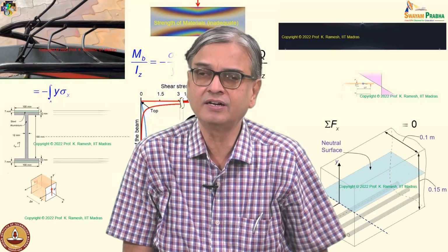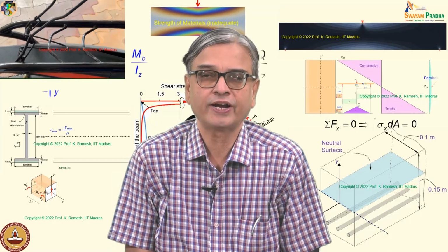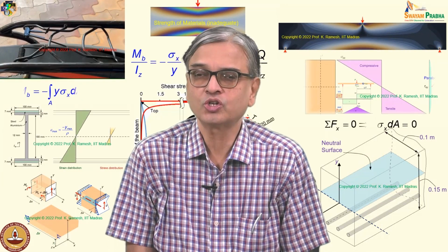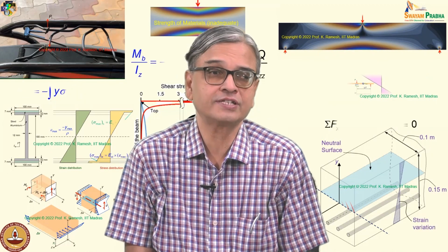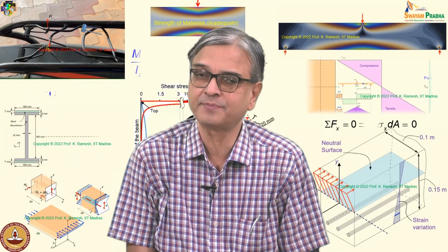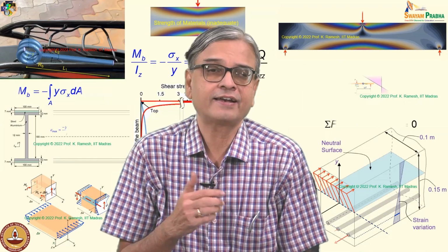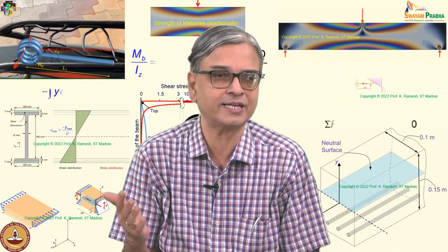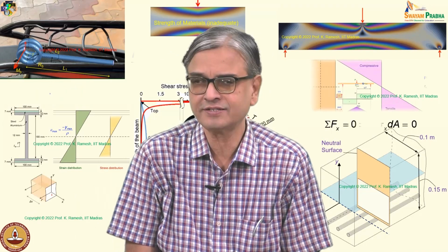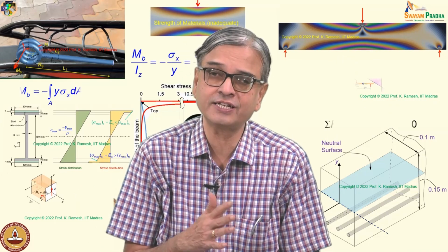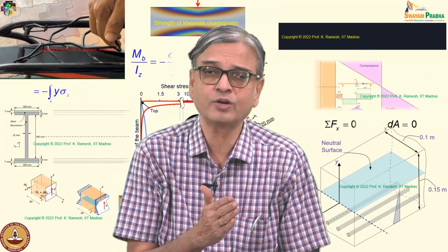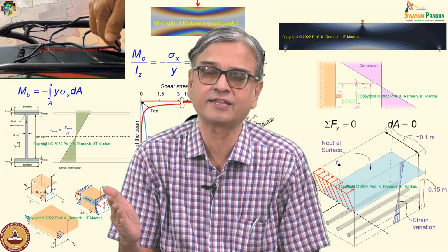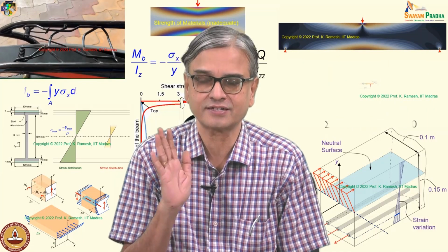See, we have learnt in the previous classes how to find out the bending stress and also the shear stress induced in bending. When you have shear force transmitted by the beam, you have shear stress introduced. When it transmits only bending moment, that happens when I have only 4-point bending, transmitting only constant bending moment, you get bending stress. And when I have a combination of shear force and bending moment, we said look at the bending moment diagram, pick out the bending moment and the shear force, use these equations to calculate the bending stress as well as the shear stress.